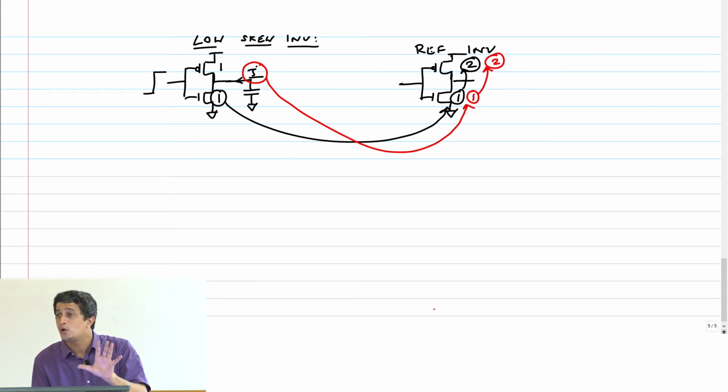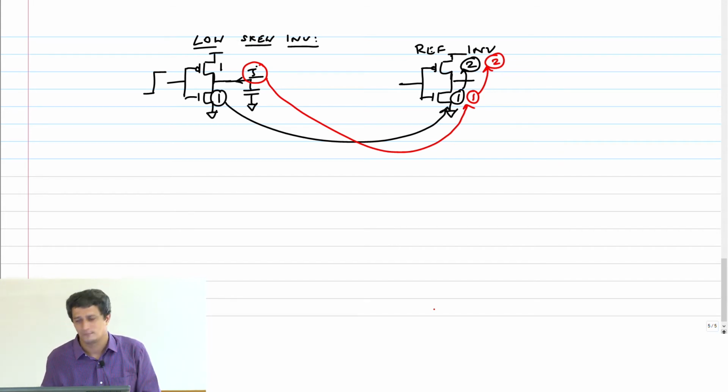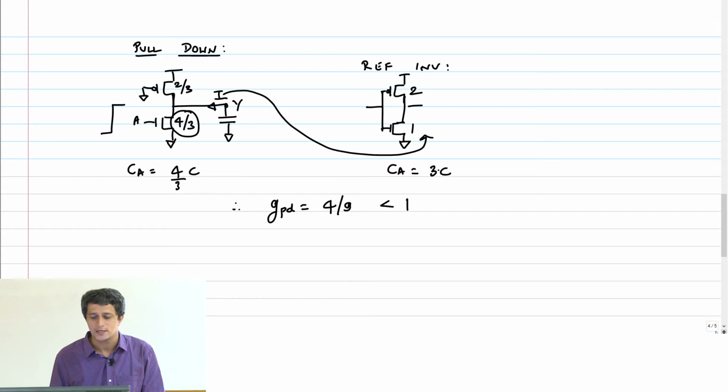So what we have been doing till now is perfectly consistent with what I am telling you now for the pseudo NMOS case, because all the current from the load went through the NMOS, or all the current from the PMOS went into the load. There was no current splitting there. So in the pseudo NMOS case, you only have to make sure that this current is what I have to find.